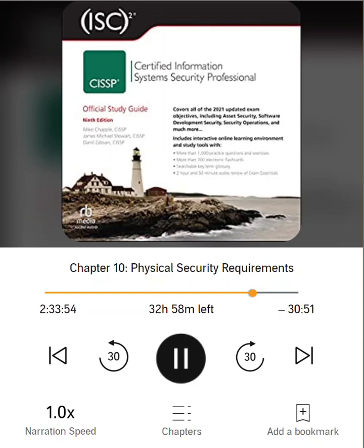5. What are the 3 main types of proximity devices and how do they work? Answer. A proximity device can be a passive device, a field-powered device, or a transponder. The proximity device is worn or held by the authorized bearer. When it passes near a proximity reader, the reader device is able to determine who the bearer is and whether they have authorized access. The passive proximity device has no active electronics.